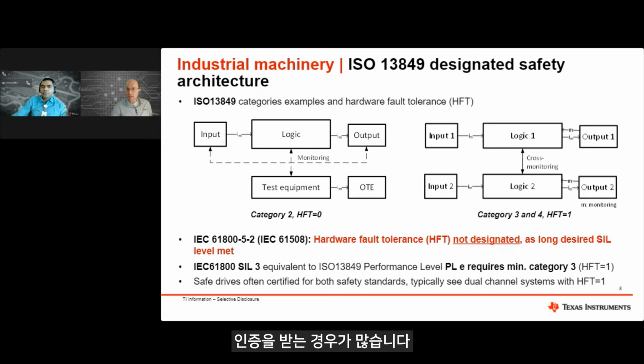Let us look at what the requirements drive in the automotive functional safety architectures. There are key differences that we need to understand between the industrial and automotive use cases for the functional safety. In an industrial system, the safety function is typically applied to an equipment under control, or EUC, that is clearly identifiable and separable from the safety functions. This distinction between the safety function and the intended function is not always possible in case of automotive. For example, traction inverter system in the electric vehicles is also implementing the safe torque functions for an electric vehicle. The safety function is tightly integrated with the intended function.